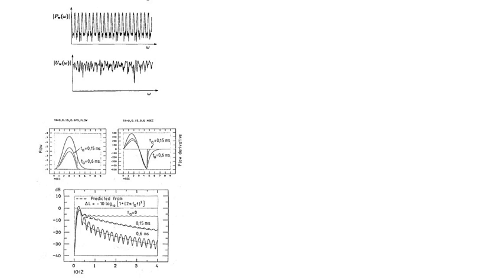So the figure at the bottom shows a whole bunch of different spectra for different parameters of this glottal excitation model, but the one that's most typical is the bottom spectrum, where you see harmonics of the pitch frequency, but those harmonics are largest at low frequencies, and they become much, much smaller in amplitude as you go to higher frequencies. And we see the effect of this in real speech spectra.